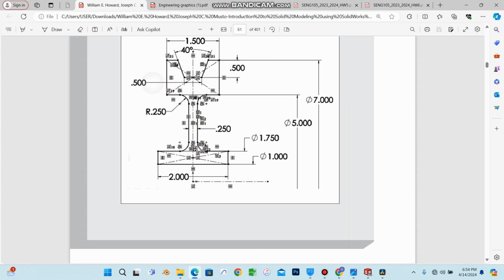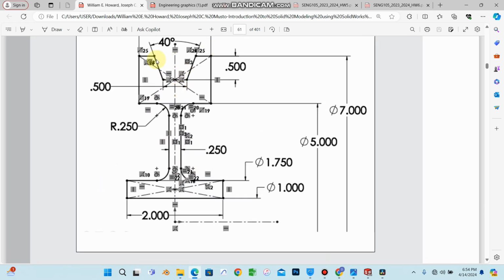This is the shape that we wanted. But the first thing we did, we added the rectangles, did revolve boss, and then we later drew this sketch and then made a cut. But you can just make this sketch. We can just add it, and then it will be just one full sketch. Then we can use the revolve boss and we will get a similar thing. So we'll be making use of the fillet, the trim entities, and that.